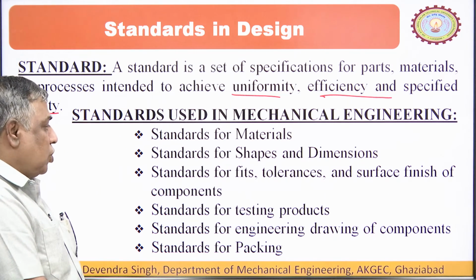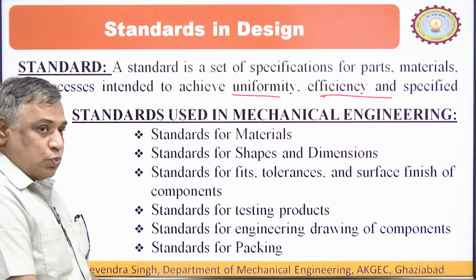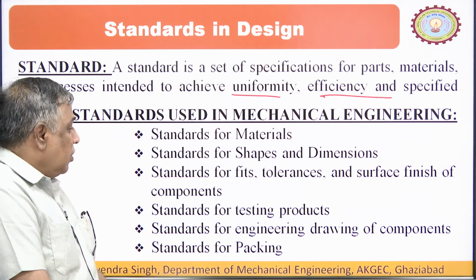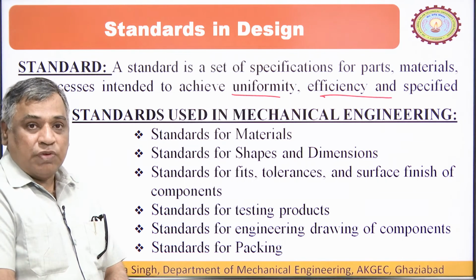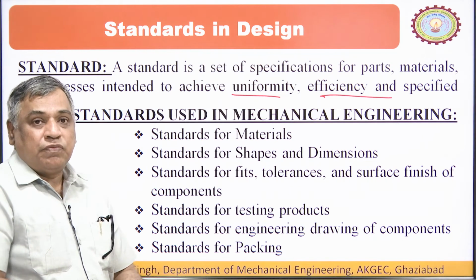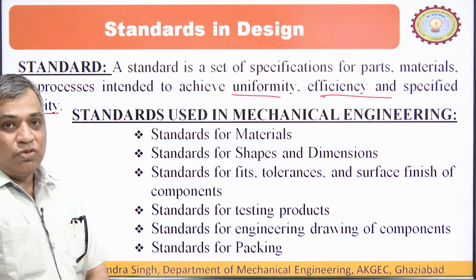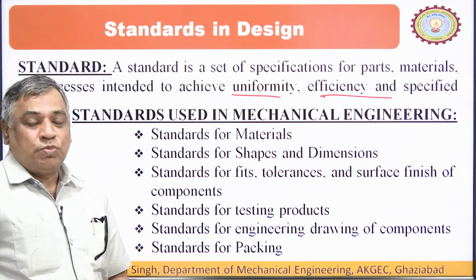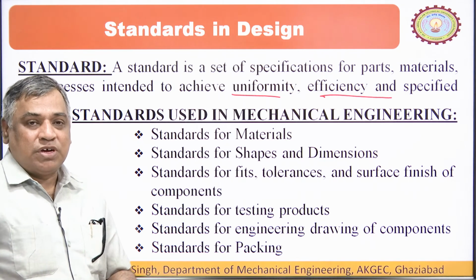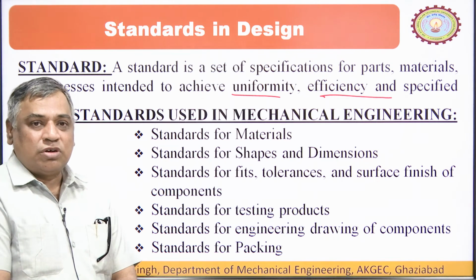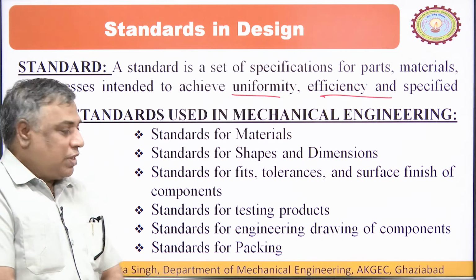Standards for fits, tolerances and surface finish of components, whatever you design, what types of fits should be given. For example, if you fit some gear on a shaft, whether it should be an interference fit or a transition fit or a clearance fit. So, it should be specified.